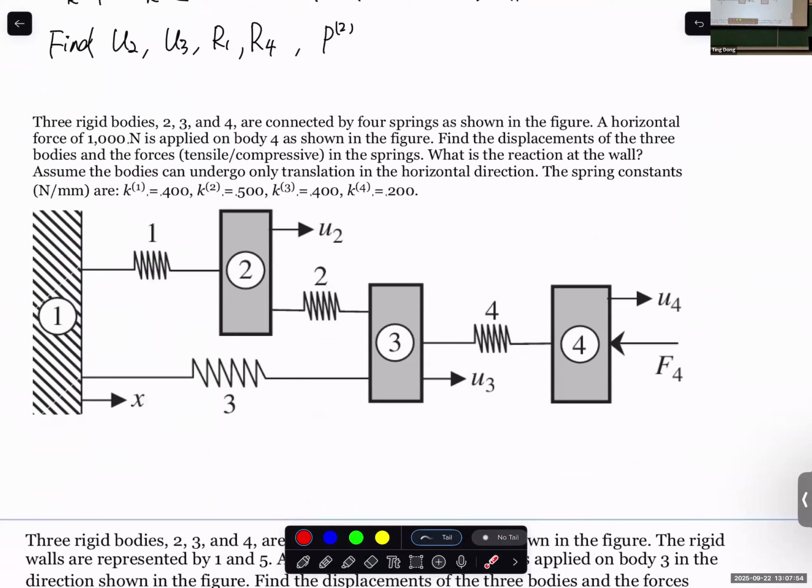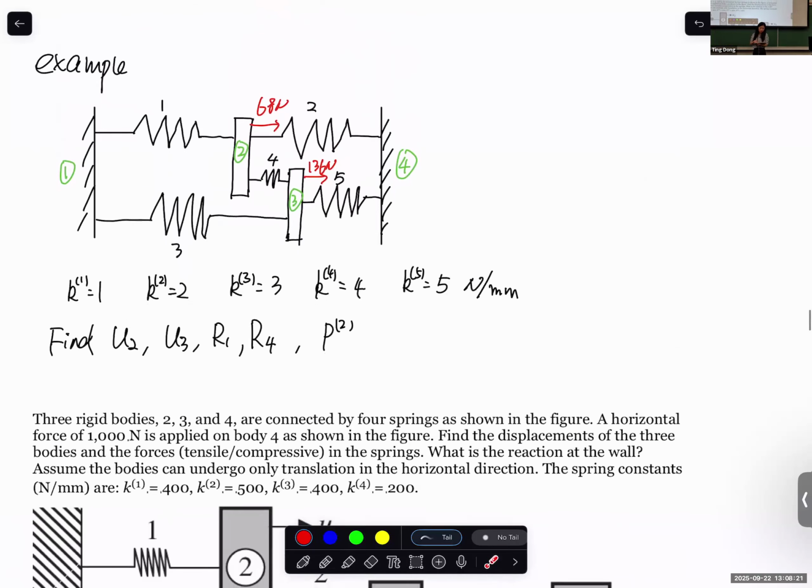Let's forget about FEA. Do you think it should affect or not affect? Doesn't, right? Again, the node order does not affect the displacement results. Let's say in a 1D situation, we put this one as positive x. If your displacement is positive 1, it means in the positive x direction for 1 meter. If negative 1, it means in the negative x direction for 1 meter. And the displacement is only for that specific node. It does not depend on which element.